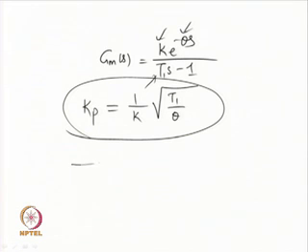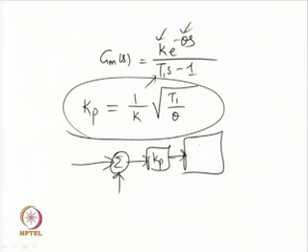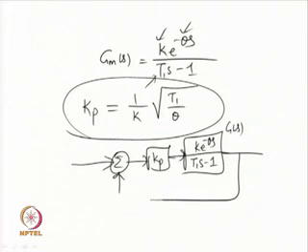the unstable system. So, when you connect this proportional controller Kp with a first order plus dead time unstable process whose dynamics is given by this real time system G(s), then for any reference input R you will get satisfactory time response Y. Why? I cannot guarantee a satisfactory response, rather I can tell that we will get a stable response, because you are using the optimum phase margin criterion. Now, we will go to the summary.